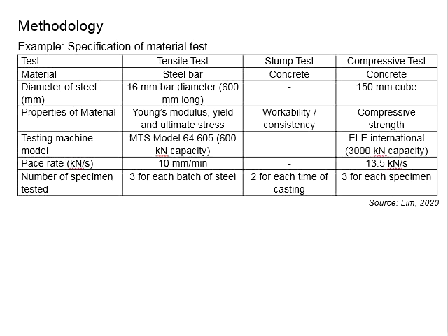On the same day that you test the beam specimen, 3 concrete cubes are also tested, assuming that whichever compressive strength is obtained from the concrete cubes is equal to the concrete strength of that particular specimen. You know that the correlation between the concrete cube and the beam specimen may not be that strong, but at least they come from the same batch of concrete and are tested on the same day.